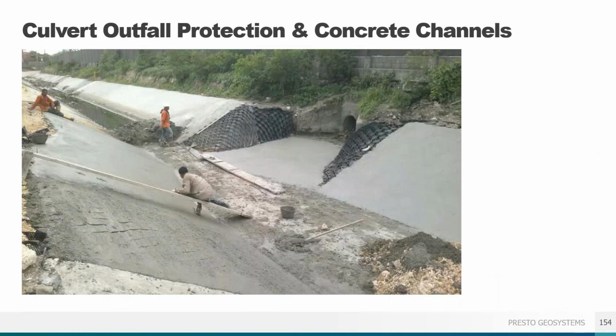Outfall areas can be challenging because they typically have high velocity and shear stress, more so than the channel as a whole. And the water in these areas is usually turbulent rather than laminar and smooth, which can cause its own set of problems. Using the GEOWEB system can help mitigate these concerns, especially when concrete is used, since turbulent flow and high velocities are no issue.